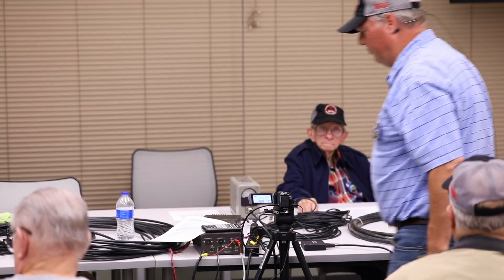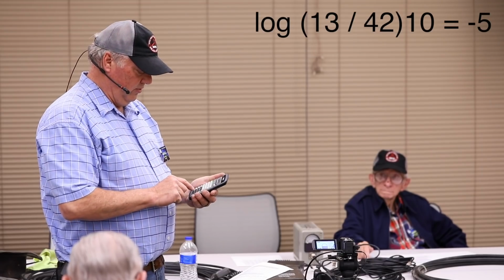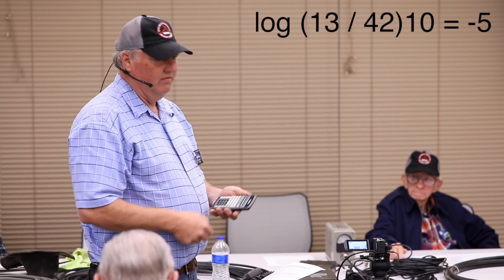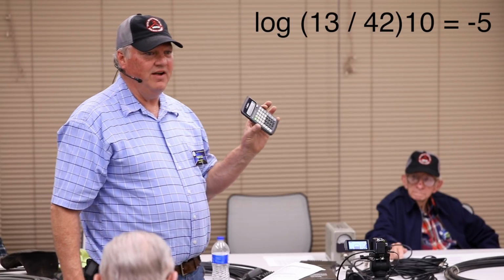And all I'm going to do is push the button on the radio. Oh, look at that. Yeah, 13. Each of the lines past the 10 is 2 watts. So it's about 13. So we'll do the same thing again. We'll go 13 divided by our 28. Excuse me, it's 42. It's about 5, right? So it's about 5 dB down.